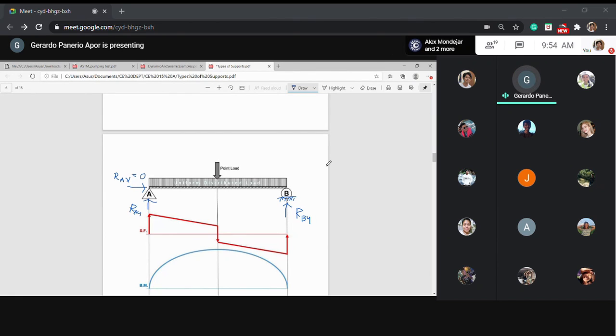You need to apply equilibrium to the external reaction so that all external forces are determined. The given ones are no problem, because they are already given. But the unknowns, just like the reaction, are not yet known before you solve them, but they are there. Only that you need to know the magnitude of it. You cannot determine it unless you solve it using the equilibrium equation.